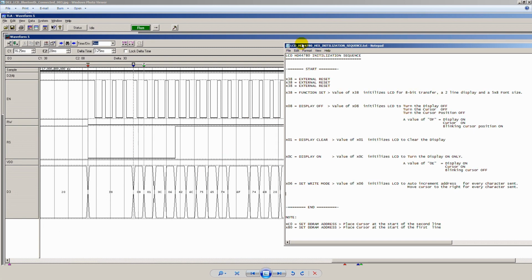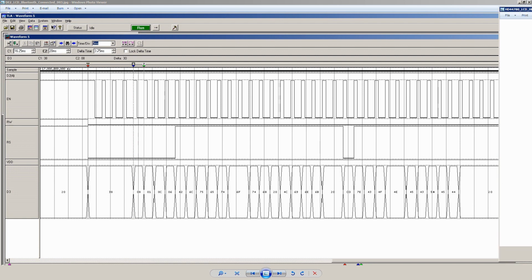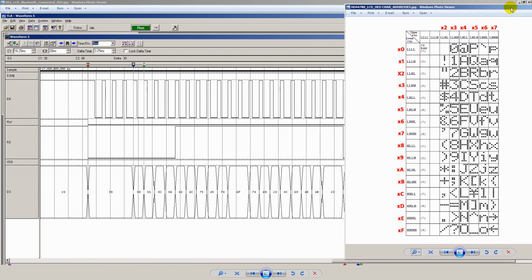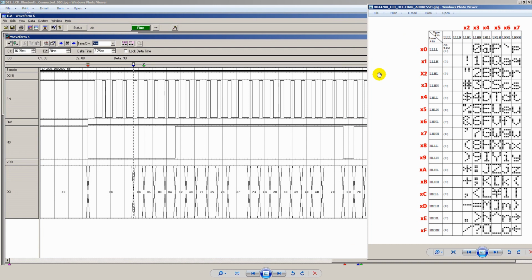So what we're going to do now is I'm going to bring in the chart that I have, where I've displayed the hexadecimal equivalent of the upper and lower 4 bits to explain it, just so you can get a little bit of a better picture of how it works. So for instance, we have all this information here because we're in a logic high on our RS value. With every falling edge on the enable line, that's essentially sending a specific character to the screen.